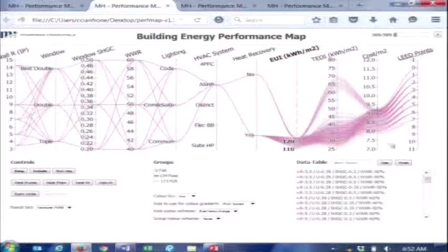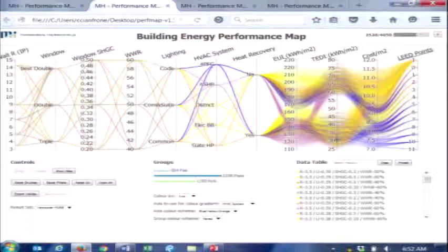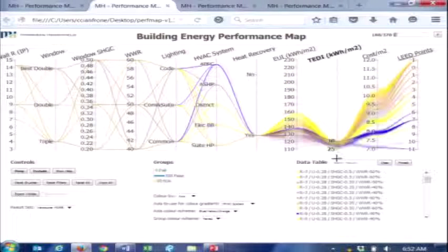You don't necessarily minimize costs. You don't necessarily minimize thermal demand, so you're not driving good envelopes. You can see on the far left here, I could still use a really crappy envelope and meet my really low energy use intensity just by throwing technology at it, by using heat pumps. So what they're looking at now is, maybe thermal energy demand is the right approach, and they're coming up with targets where, if we force people to drive better envelopes, with really low thermal energy demand, then the mechanical system becomes irrelevant, and you now have to have better envelope systems.